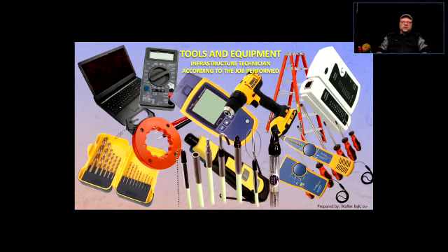And as far as using lubricants, get the ones that are designed for cable installations, right? Any hardware store right now will carry those lubricants. They are designed for that. What do I mean by that? I have seen people, because they ran out of lube or they forgot it, and they have to install a wire, just go to the washroom and get a paper towel and put some liquid soap on it, and that gives you enough lubrication. Don't do that. Please do not do that.